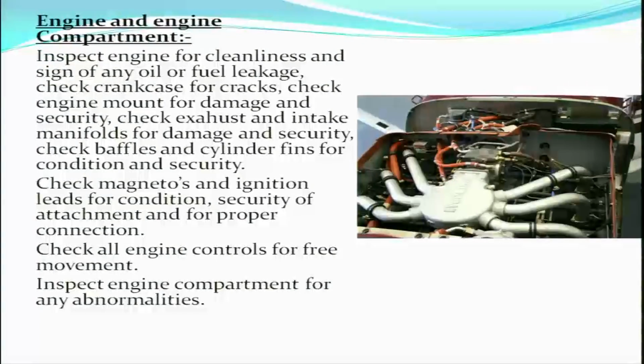In the engine compartment, inspect engine for cleanliness and signs of any oil or fuel leakage. Check crankcase for cracks. Check engine mount for damage and security. Check exhaust and intake manifolds for damage and security. Check baffles and cylinder fins for condition and security.